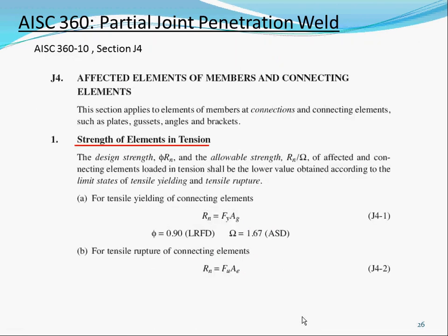That's why when we design the gusset plate and cut it, we account for this 1/8 for the weld. When we cut the steel plate, we trim it like this. Is this the bracket? The knife plate. Okay, the knife plate. So that's CJP and PJP.